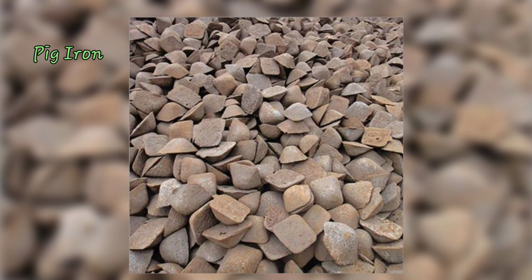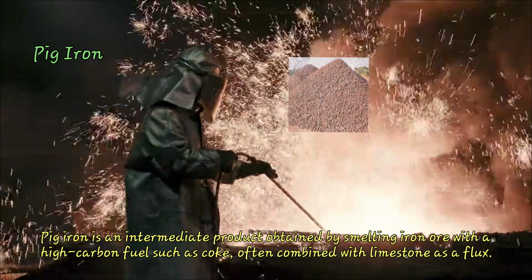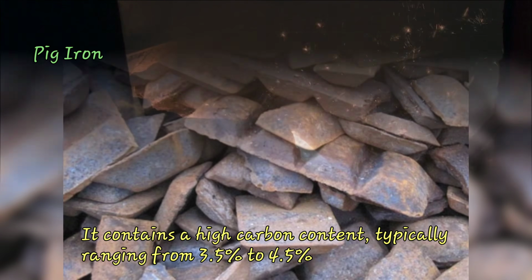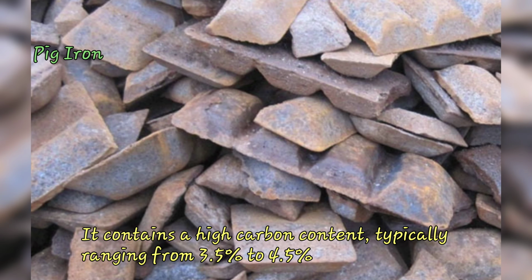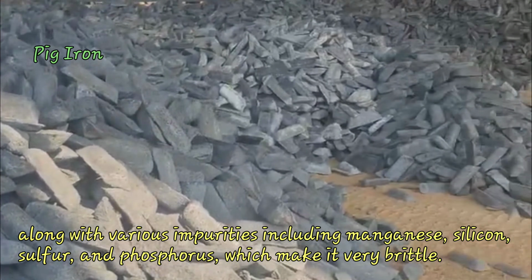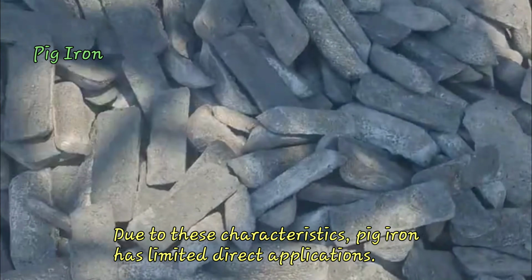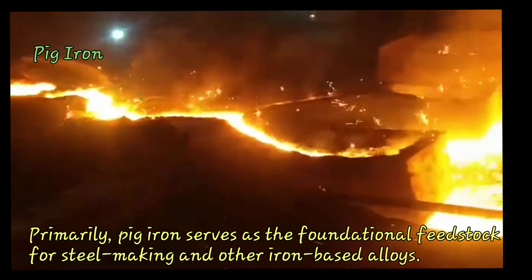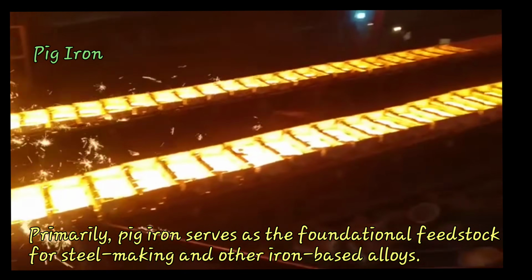3. Pig iron. Pig iron is an intermediate product obtained by smelting iron ore with a high carbon fuel such as coke, often combined with limestone as a flux. It contains a high carbon content, typically ranging from 3.5% to 4.5%, along with various impurities including manganese, silicon, sulfur, and phosphorus, which make it very brittle. Due to these characteristics, pig iron has limited direct applications. Primarily, pig iron serves as the foundational feedstock for steel making and other iron-based alloys.